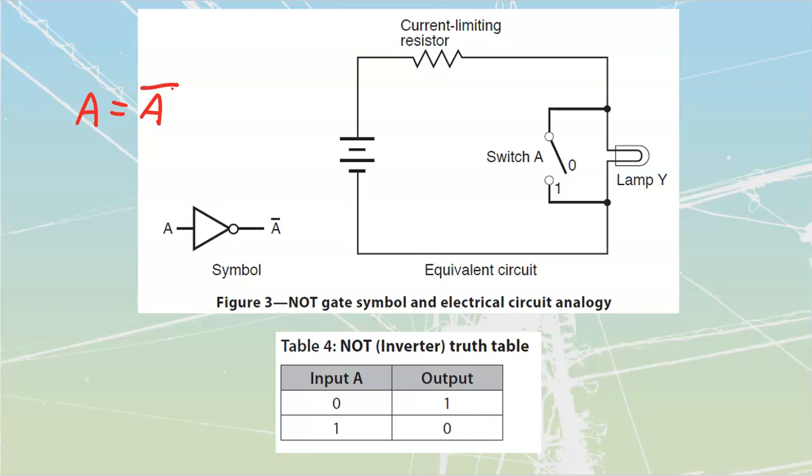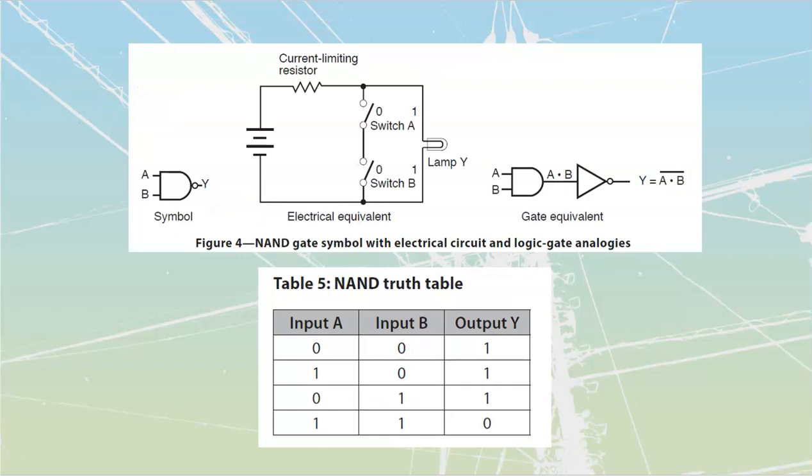Okay. You ready? Watch that bubble. What do we have over here? Over here we have the NAND gate. Note that the NAND gate is composed of an N and the AND over there. It's an AND gate that is going to be inverted on my output. It's the same thing as if I have an AND gate in line with an inverter.